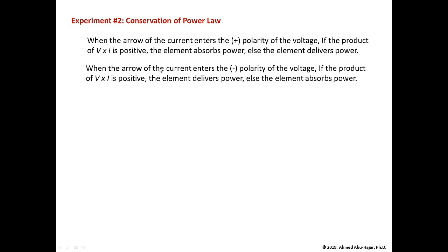However, if the arrow of the current enters the minus polarity of the voltage, if the product is positive, then it is delivering power, else the element is absorbing power. Those are the two rules I have here.